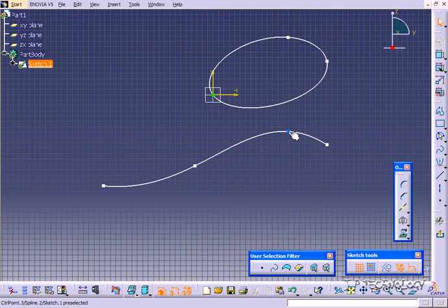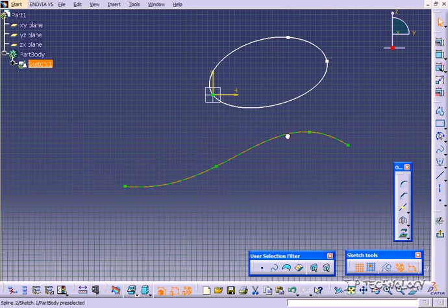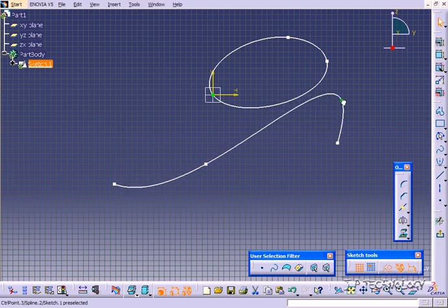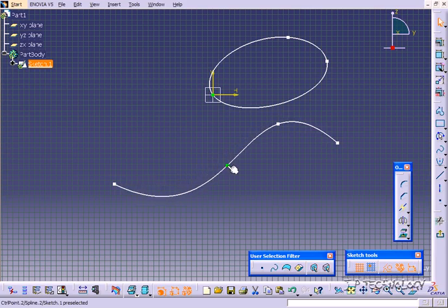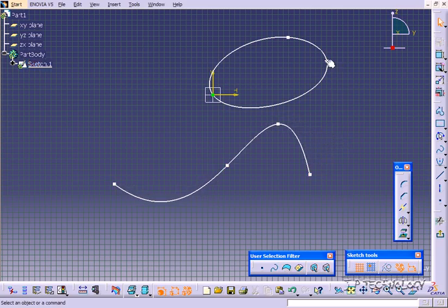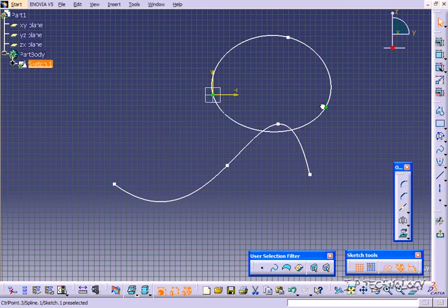Now again, like the other sketches, you're able to manually adjust. So when you're trying to adjust it, you can click on the spline and move it in any position. But say you actually want to change how it looks, you'd have to click a point, drag, and move it around. Especially with the spline, because it has a very organic feel and look when you're playing with it. It allows you to really massage your spline and give it the look that you want. So you're able to do it to just the profile, or you can do it to a complete sketch such as this.